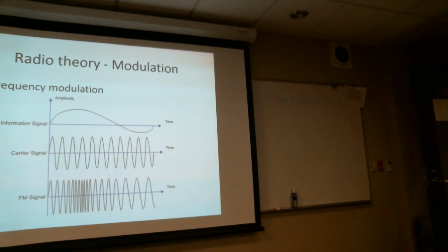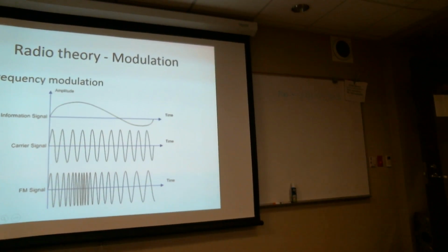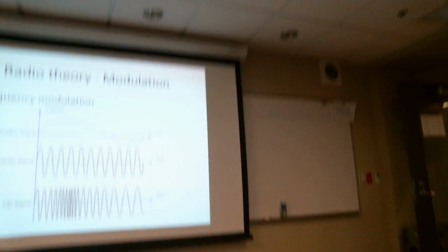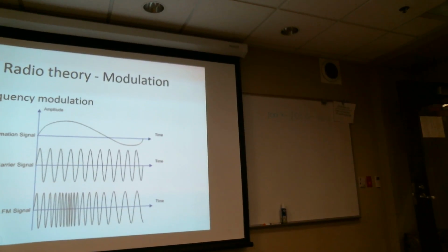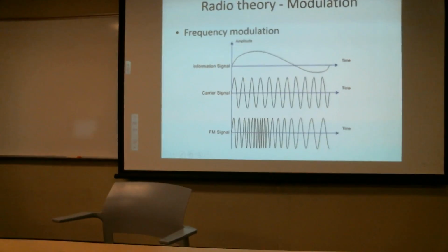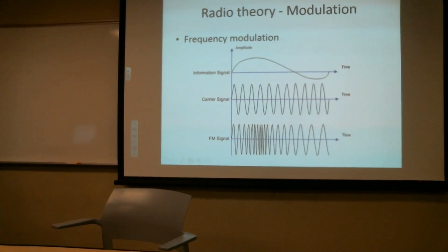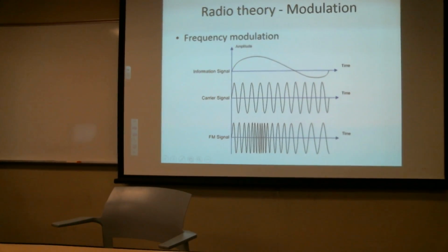So that means I can't fit as many channels over some bandwidth, right? So I'm going to have to make sure my tuners are pretty accurate. This is why, particularly as you're driving down the road and the signal starts getting a little bit weaker, and you've got another one that's pretty close to it, and they're both reflecting and echoing, and Doppler effect is occurring, sometimes on FM particularly, you'll hear two channels bleeding over, okay? Because they're close enough to each other, whatever it is, 103 and 101, that you start hearing both of them, okay?